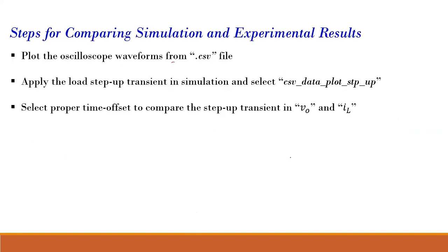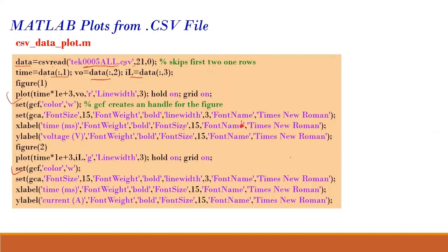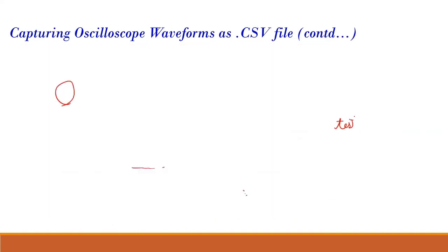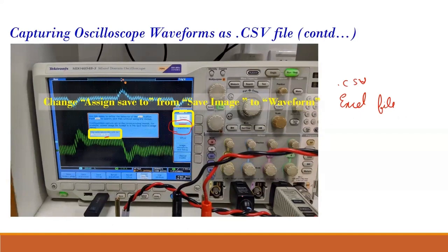And one more thing I'd like to tell: when you're doing these hardware things, you can test the probe. You see over here, this is the ground and this pin is there. You can connect the probe over here, and it should show a square wave.